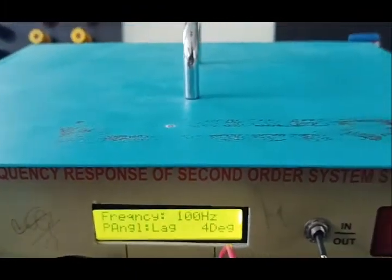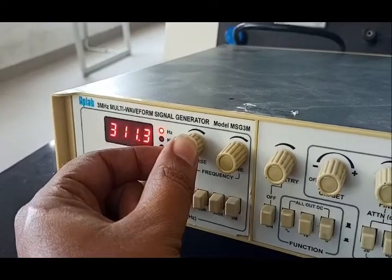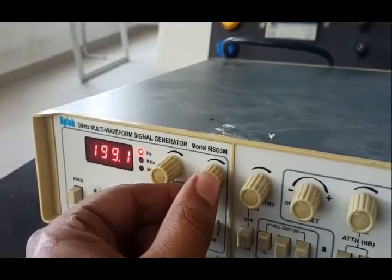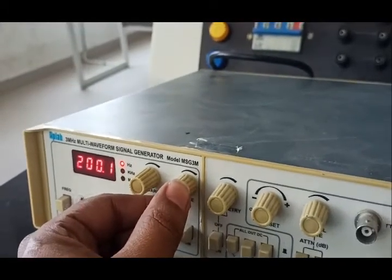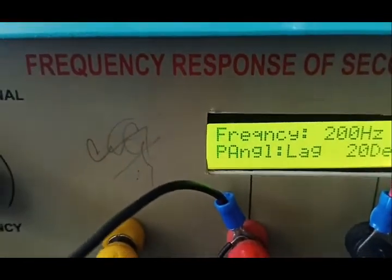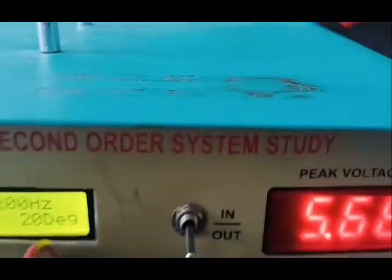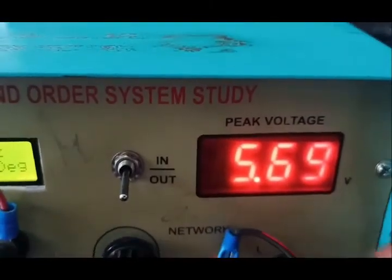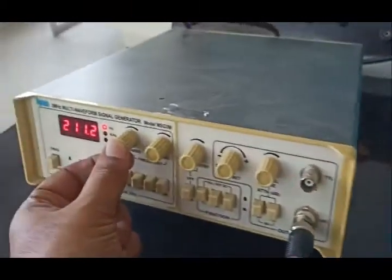So now let me increase the frequency. You can adjust exactly for 200 hertz using coarse and fine, and you can observe the frequency of 200 hertz. So what is the phase angle? It is 20 degree, and you need to record that it is lagging. And what is the output voltage? It is 5.69.